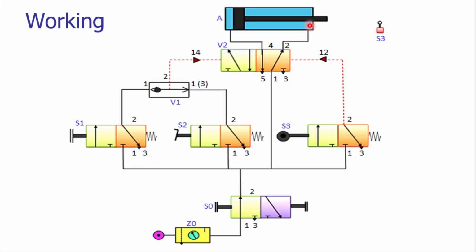As the pressurized fluid has been applied on the other side of the piston rod, the piston rod will be displaced from right to left direction. In this way the retraction or contraction of the piston cylinder arrangement will be carried out. Thus we have seen how this variety of pneumatic elements helps to have an efficient and systematic operation of the pneumatic based circuitry for the desired application. In this case it is displacing the components from the magazine.